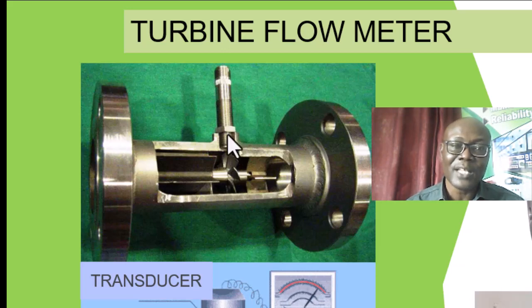What this pulse counter does is that it counts; it is a pickup, anyway. It counts the number of times each of these blades passes through it. So when each blade passes, it generates a pulse. When another blade passes, it generates another pulse. Okay, so the number of pulses compared to the time that it takes for those pulses to be generated will give us the flow rate, the volumetric flow rate.